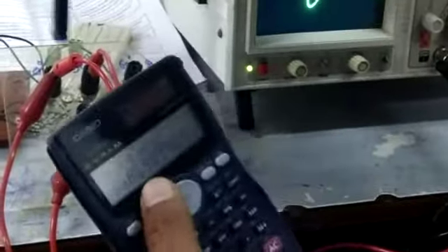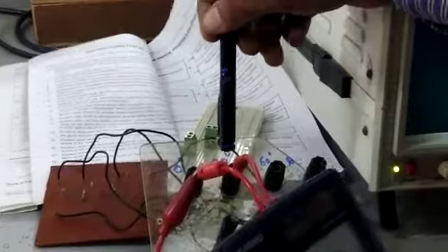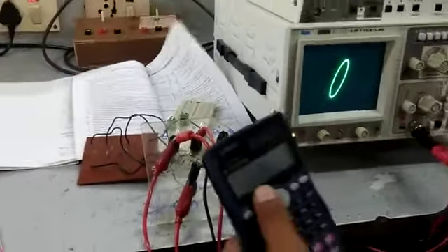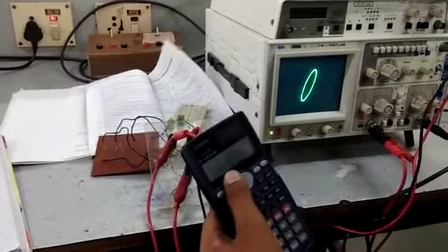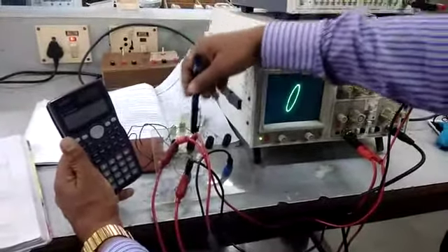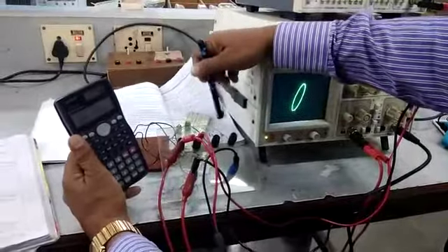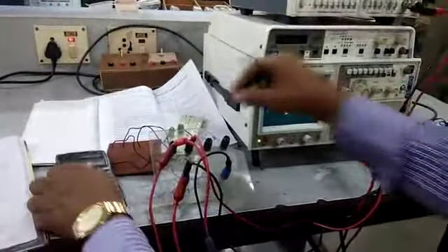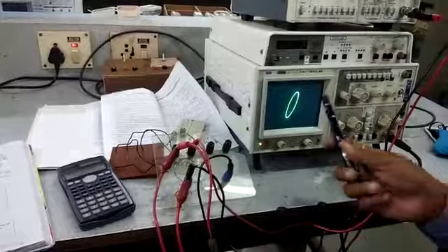But right now, see here, my phase is 30 degree. Means there is a difference between these two. Actually I should have got 30, but I got 36. That means there is an error. Now similarly, you can change the phase from this RC network. Then your pattern also changes, and the values of x1 and x2 also change.